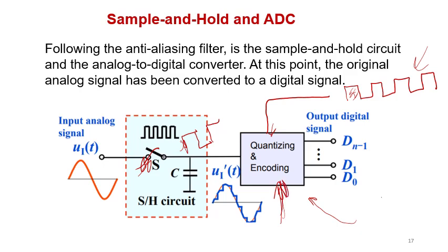Fine. Now, what if the pulse generated by the switch comes during the interval when the clock pulse is low? It's going to be lost. That's why we put this capacitor, to keep the pulse in it until it's taken by the encoding circuit.